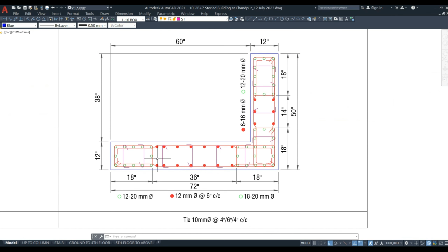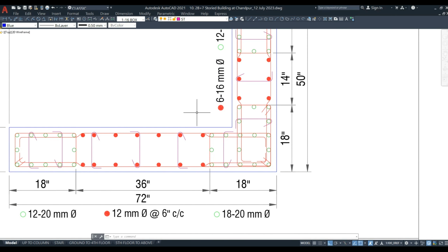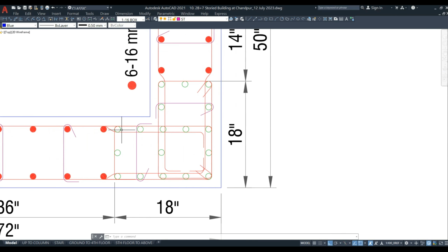And in case of a compound shear wall, the only complexity you have is at the junction. Okay, at the junction. So at the junction, how you will arrange your hoops, this is a matter of concern. So you can arrange your hoops like this. This is a complete hoop. This is a complete hoop, and they overlap on each other. And this should be good because this hoop interlocks this hoop. So this is a good practice. So the corner should be well protected.